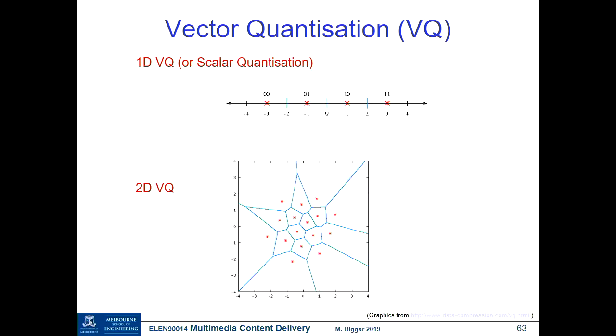But we could also do multi-dimensional quantization, vector quantization. In this two-dimensional illustration, we've got two variables, two quantities that we're quantizing. It doesn't matter what they are. But as a result of analysis of the probability and the resultant distortion when they are quantized, we've decided that anything within this particular blue boundary is quantized or rounded and represented by that single red point there, two coordinates. And similarly, anything within this range is to be represented by another pair of points there. So quantization may be multidimensional.